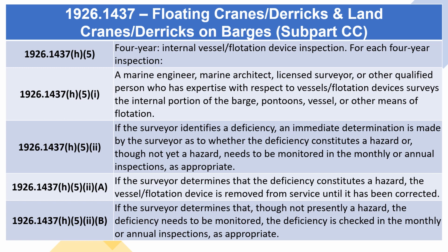1926.1437 H5-2 A and B, if the surveyor determines that the deficiency constitutes a hazard, the vessel/flotation device is removed from service until it has been corrected. If the surveyor determines that, though not presently a hazard, the deficiency needs to be monitored, the deficiency is checked in the monthly or annual inspections, as appropriate.